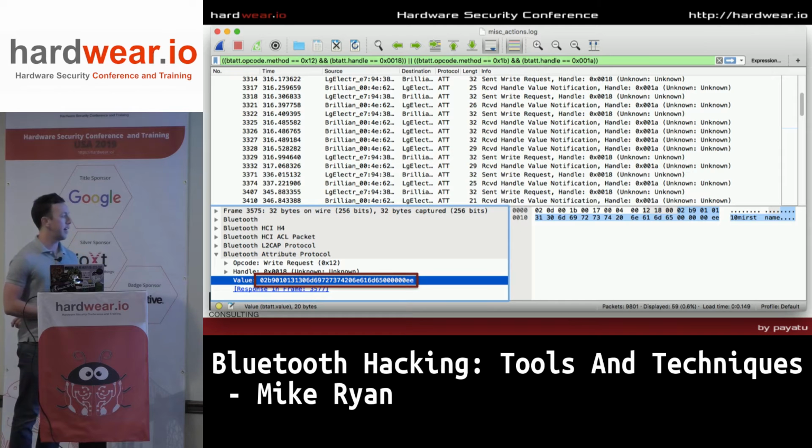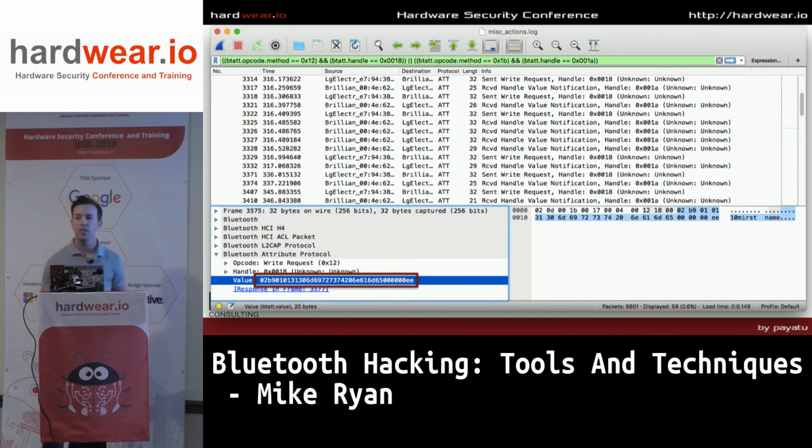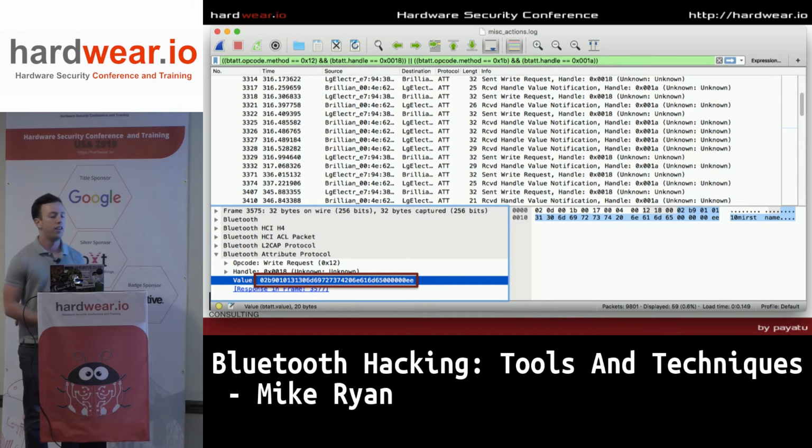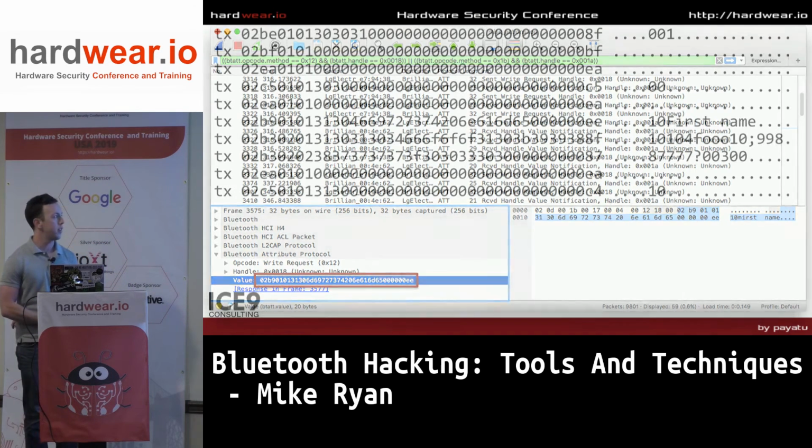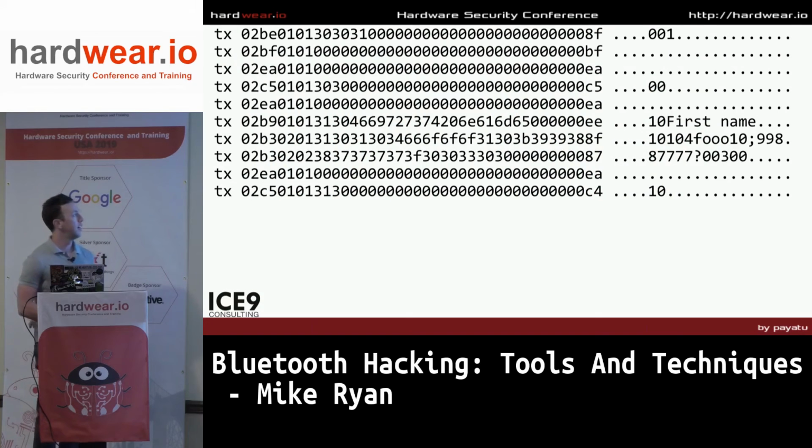And we can see something that amounts to another hidden serial port, surprise, surprise. And if you start to look in the decoded protocol here, there's actually some ASCII data. So that's good. This is not really even binary reverse engineering at this point. This is a protocol that we can really make sense of. So exporting the data into JSON and writing another basic Wireshark parser,